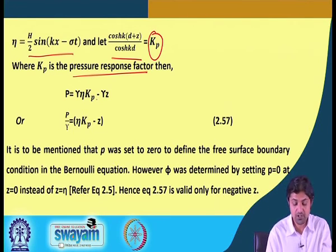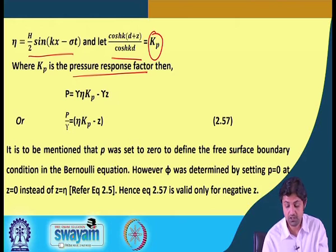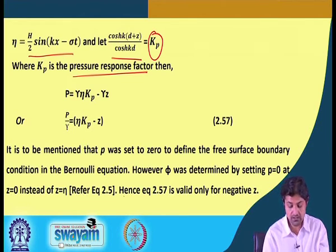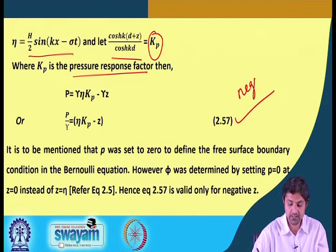Now, it is to be mentioned that p was set to 0 to define the free surface boundary condition in Bernoulli's equation, if you remember. However, phi was determined by setting p equal to 0 at z equal to 0 instead of z equal to eta. Hence, this particular equation is valid only for negative z.